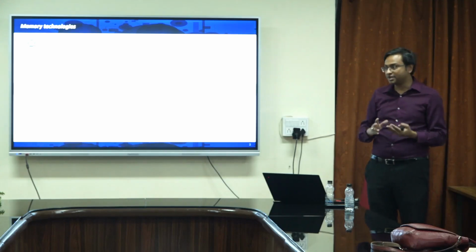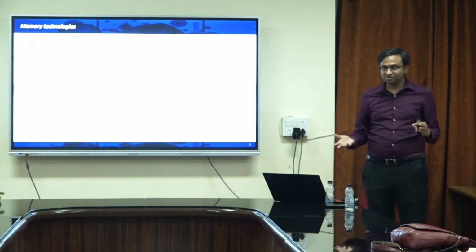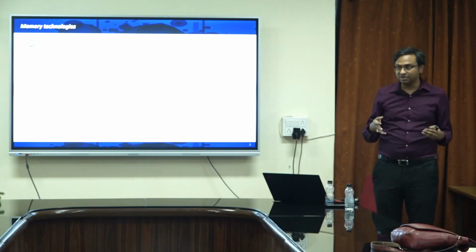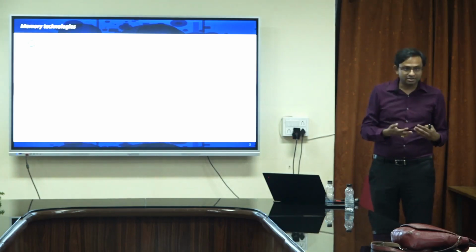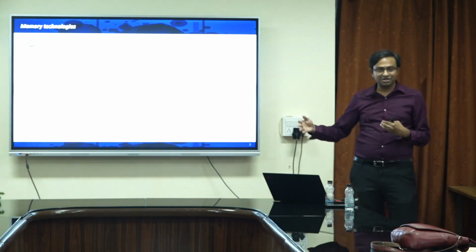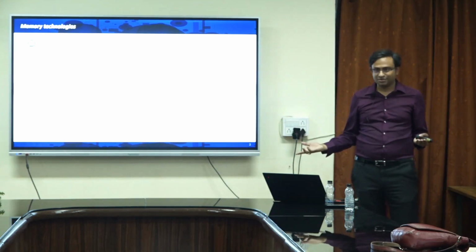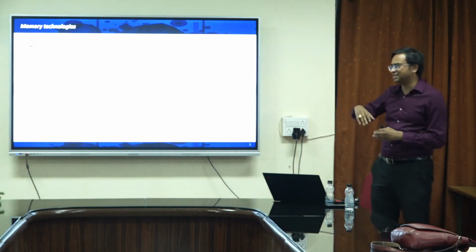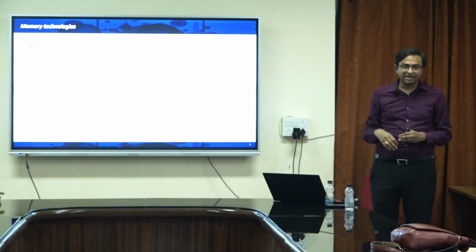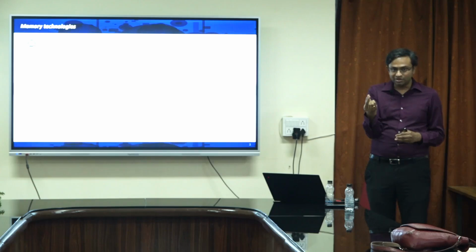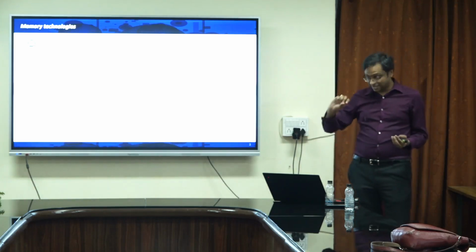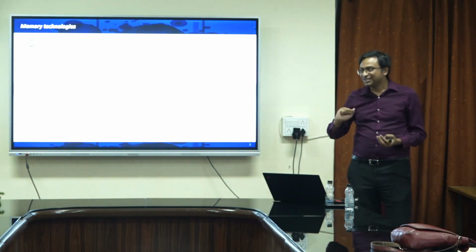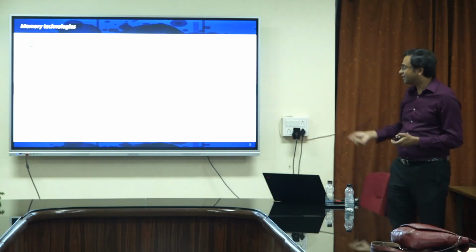And how reliable it is. If today you store one image and it got converted into another image tomorrow, you don't want such a memory device, right? So you need to really make sure it is reliable. It has to be thermally stable, right? Today it is winter, and then I open my information in summer and everything is flipped. That's not good, so thermal stability has to be there. It also has to be radiation resilient. That's mostly for space application. But in general, because the memory devices are so small, cosmic rays are coming all the time and they can flip a bit, and then my memory information gets changed. So ideally it has to be radiation resilient.